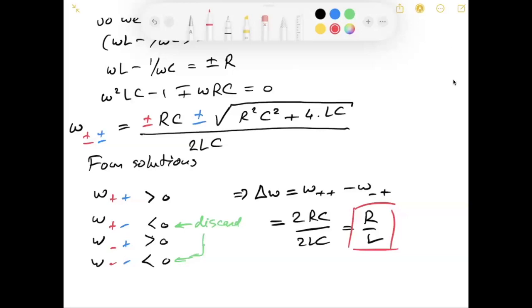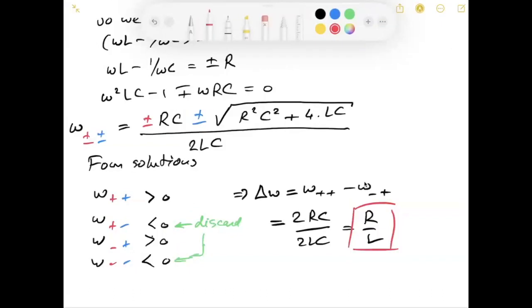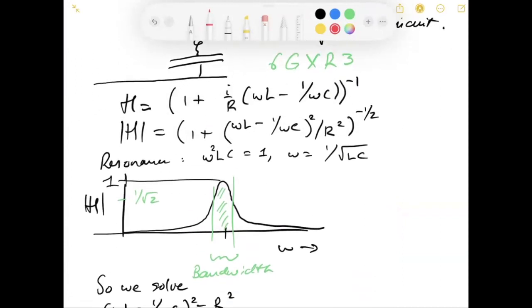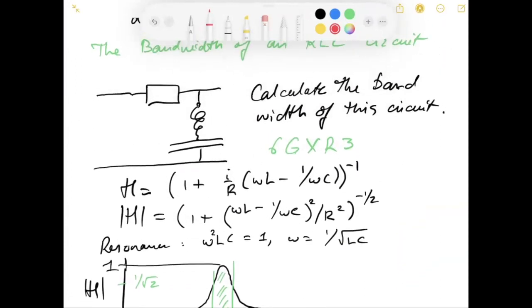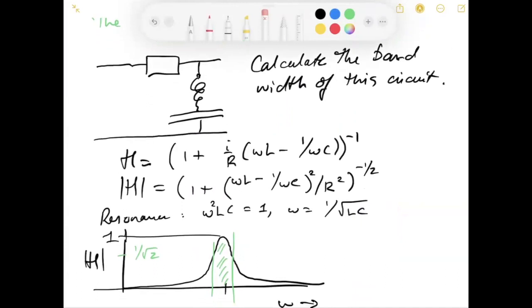All right. For those of you furiously scribbling along, hopefully you got there about as fast as I did. This is not a complicated problem. It just takes paying attention to where your pluses and your minuses go. Let's first get rid of this thing. The transfer function we get in the same way as before: 1 over 1 plus the ratio of those two impedances. Impedance number 1 is the resistor. Impedance number 2 is the series combination of the capacitor and inductor.